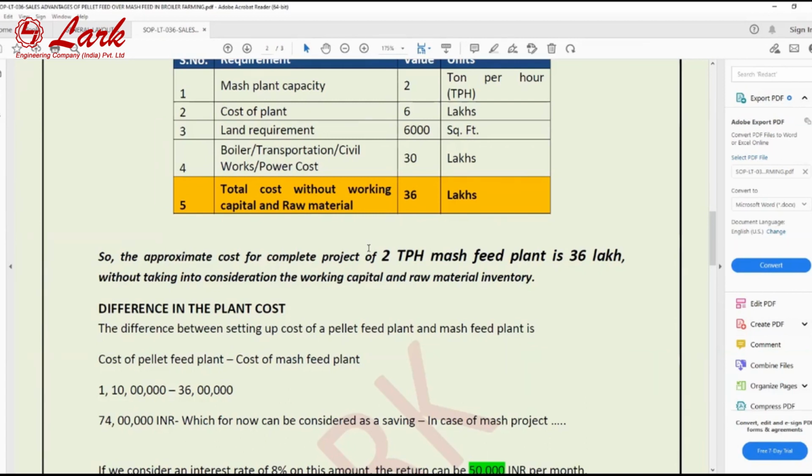And what is the power consumption you need for that? So the power required for the machinery is around 160 horsepower. In kilowatts, it is around 125 kilowatts. 125 kilowatts. I think that is achievable in my case. Actually, we have a lot of power issues. That is why I cannot go for a pellet mill, because I have maximum, I think, around 75 kilowatts capacity in my area. More than that is not available in my area. That is one of the constraints for me.